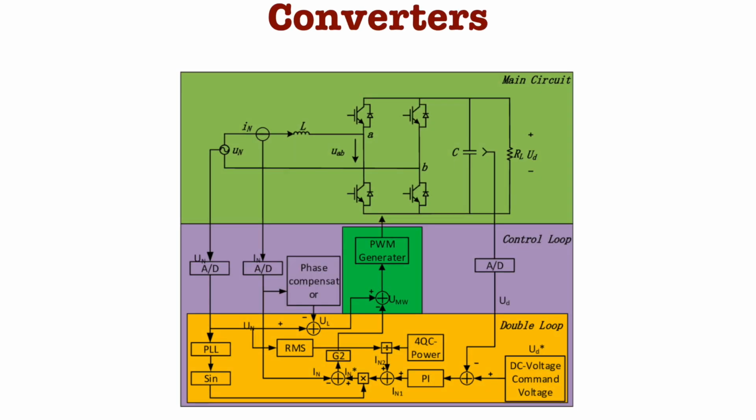These are not just simple power converters in a 4-quadrant setup, they are dynamic, capable of reversing the power flow. This functionality is vital for enabling the motor to switch between motoring and braking and forward and reverse operations smoothly. By manipulating the direction and the nature of the current, converters allow the drive to exploit the motor's full capabilities across all the 4 quadrants.